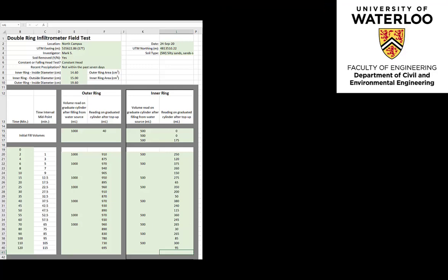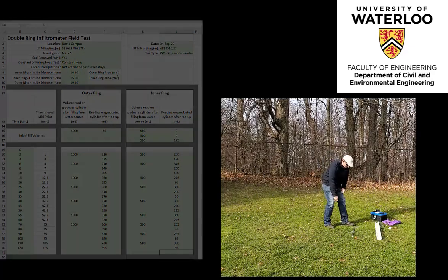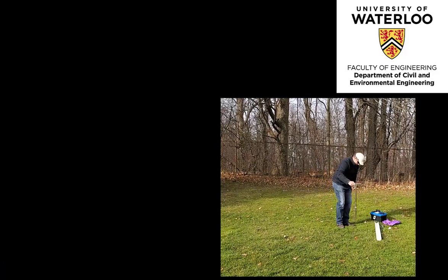Now that the infiltration test has concluded, we will complete the field investigation by advancing a shallow core to further characterize the soil horizons and collect specimens for laboratory analysis. The core should be obtained proximal to the location where the infiltration test is being conducted, but not too close, such that the in situ moisture content of the soils is properly represented and not biased by the infiltration test. Usually within 3 to 5 meters away from the infiltration test is sufficient.